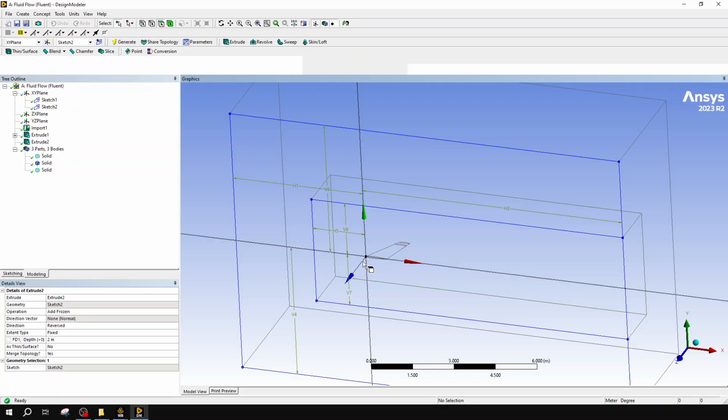So what I'm going to do for this system specifically is add my rotation of my wing into this first one. Even if I were to simulate this at 0 degrees, I'd still want to add this rotation so that when I copy and paste the geometry into future problems, I can change those parts.